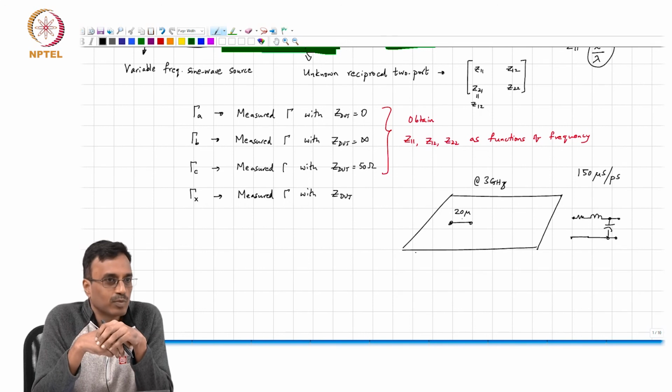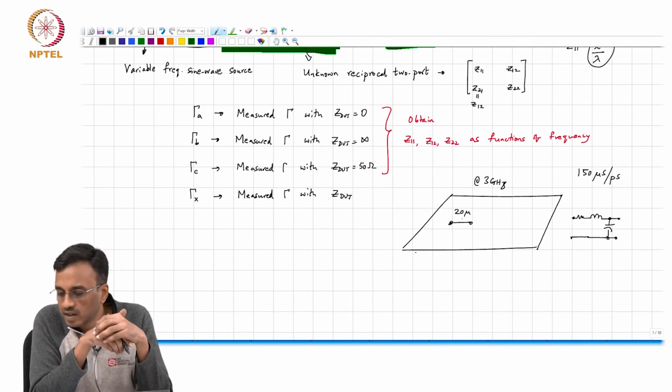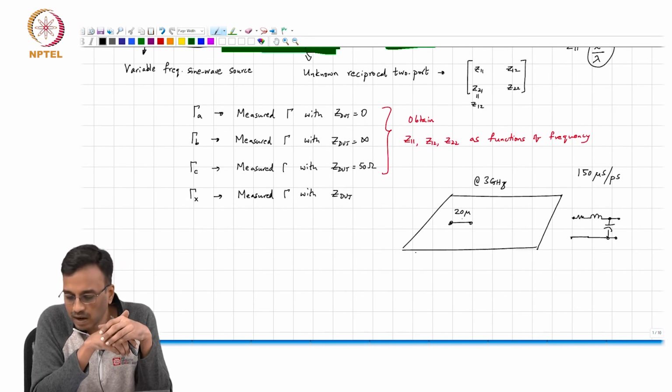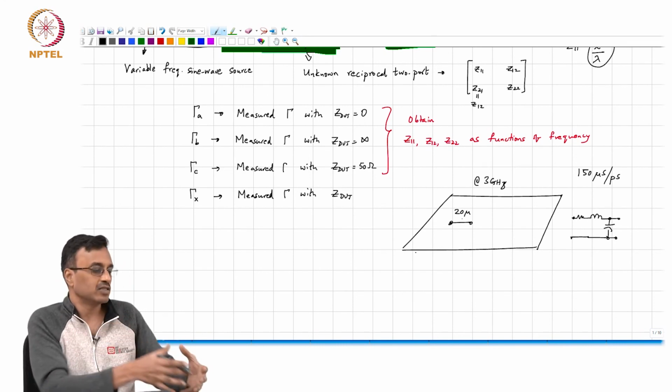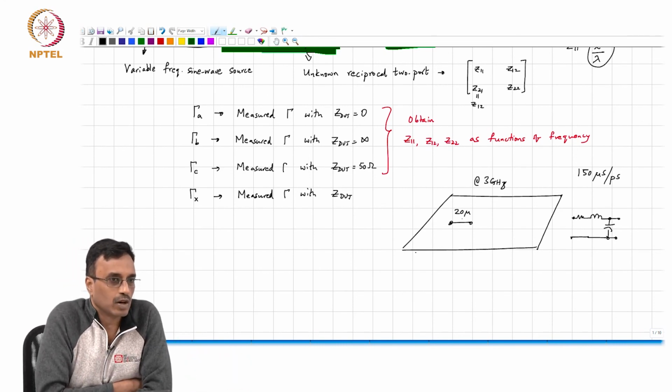So, 10,000 miles of transmission line working at 50 hertz, distributed effects become just as important and crucial as working at, say, 3 gigahertz on a benchtop table. Whereas with the same 3 gigahertz you don't have to worry about distributed effects on a chip. Does it make sense? All right.